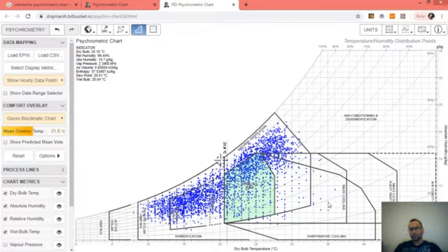We know thermal mass cooling or heating is used in locations characterized by temperature fluctuation between day and night. So the heat taken during daytime by the thermal mass is given off during night by night ventilation and night cooling. So it needs weather conditions with temperature fluctuation between day and night, which doesn't happen always in Beirut.